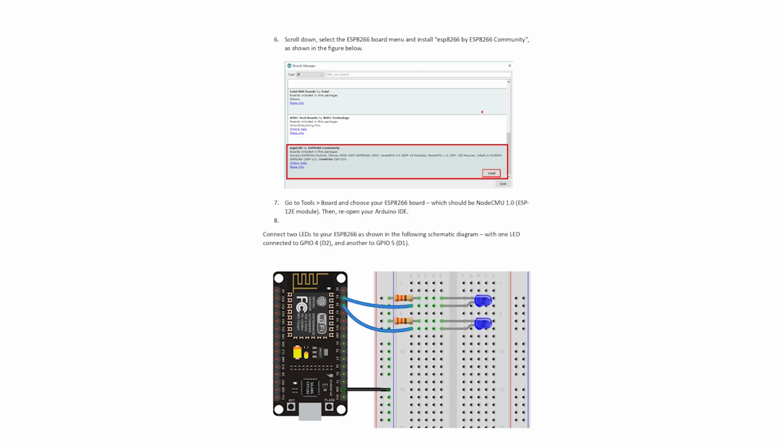We are only using this side of the board. In future projects, if you have to use this side of the board, you can use male to female connectors, because these are pins, so a female connector will go in. Here, because we are using the breadboard, it will be male to male. So we will use 3 male to male connectors. Everyone follows?